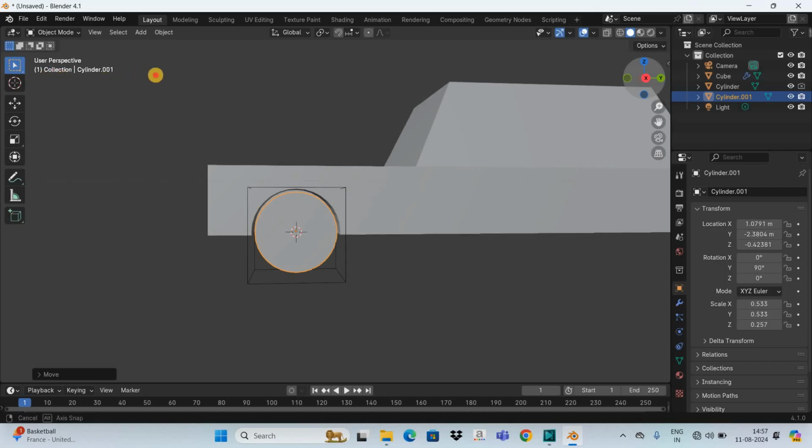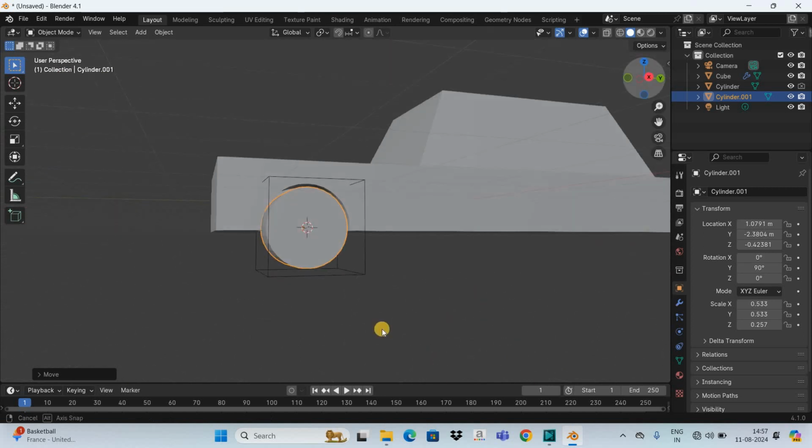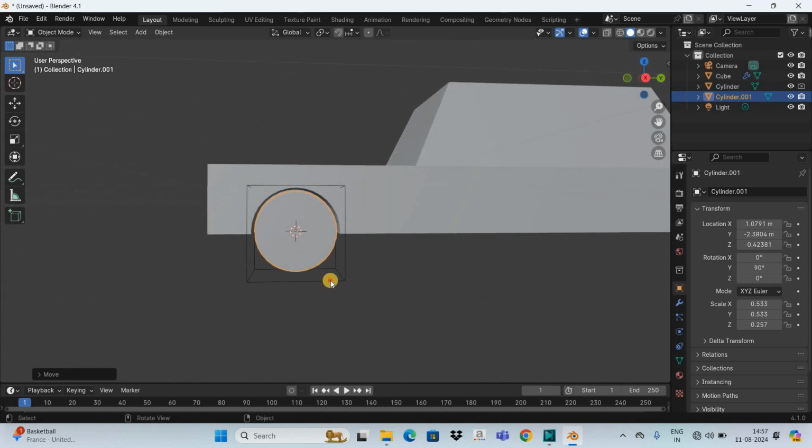So we will use the Mirror modifier to mirror this wheel on the right hand side of the car. So let's do that. First select the wheel cut, the cylinder using which we created the wheel cut. So let me name these objects one by one, because that way things will be much clearer.